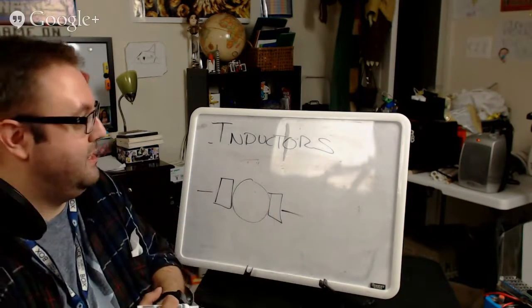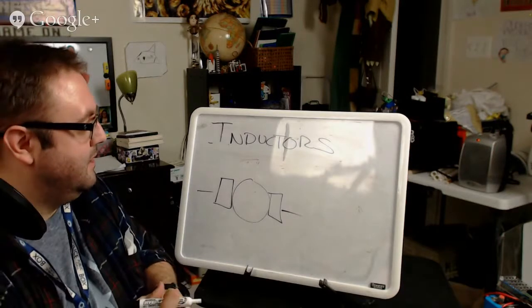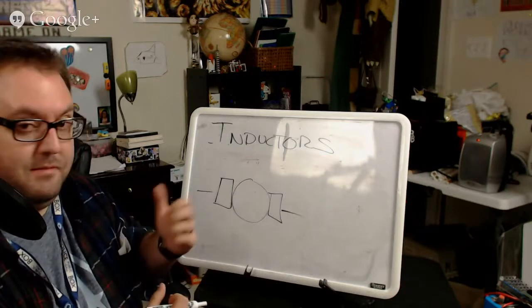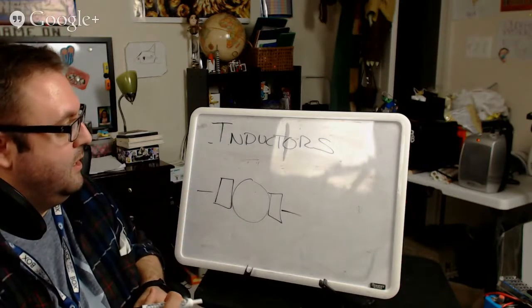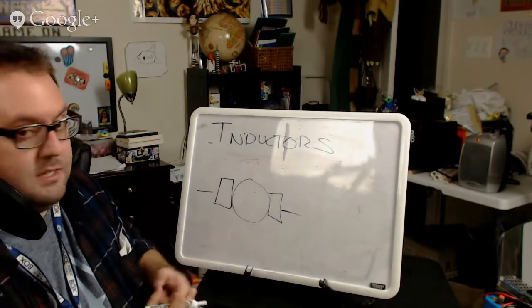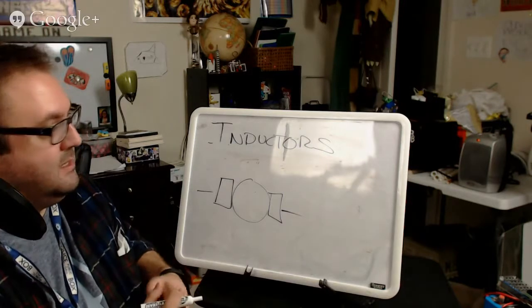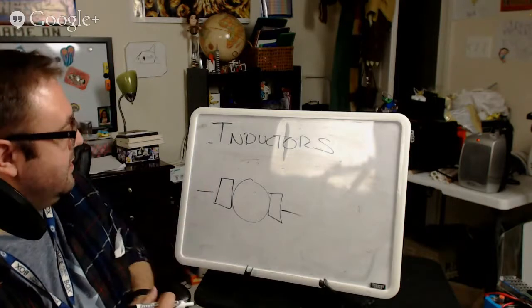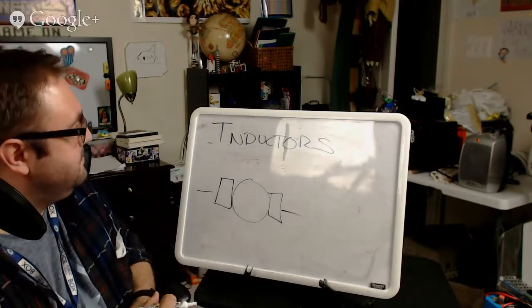That's where things like electrical generators come from. It's just the motor working backwards. Take physical mechanical motion, cause a coil to spin, which interacts with the magnetic field, and I now induce a current across the wires.